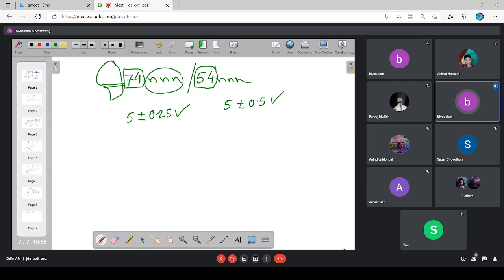Now this NNN identifies one particular device, one particular logic gate. For example, if the NNN value is 00, that means 7400, which is a quad 2-input NAND.